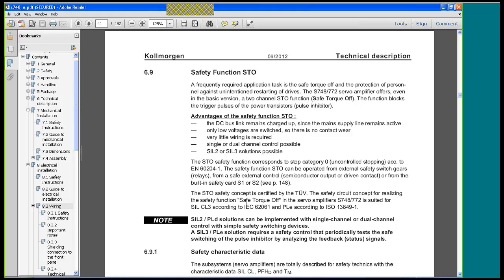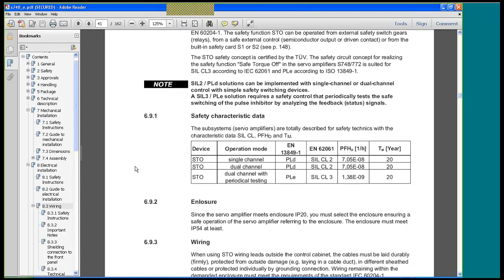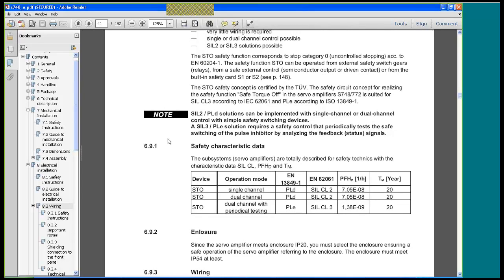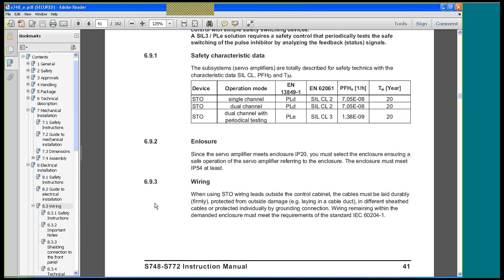So slot number 3, the last one we covered, was basically for installation of the safety card for the STO. The simple description is that there are only 2 inputs that the drive will manipulate. The STO card brings in external safety and the ability to meet the SIL levels that come in with the safety card. External wiring and external master controls are going to be necessary in order to complete the function.